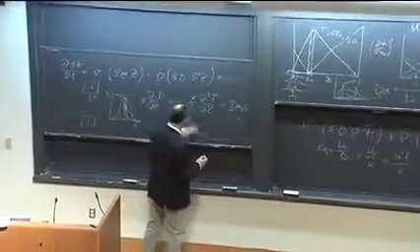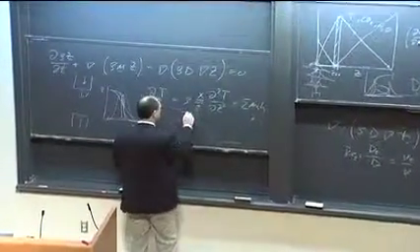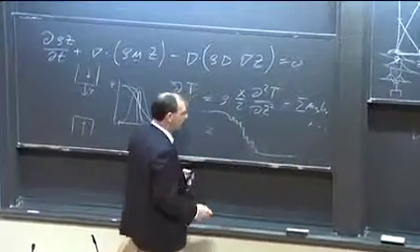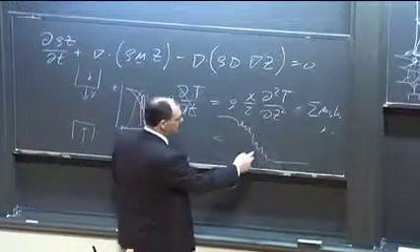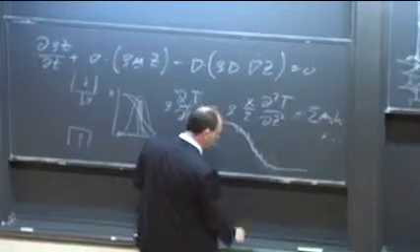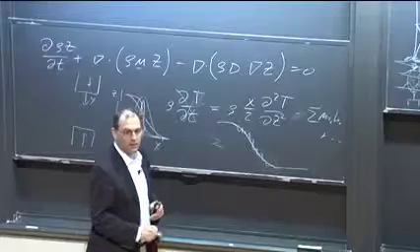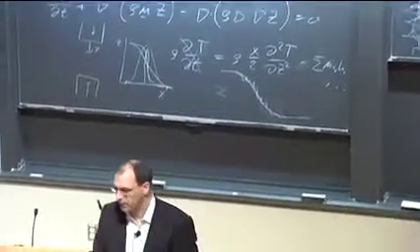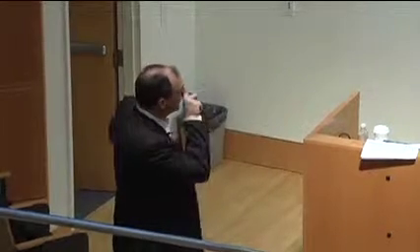Now, in the turbulent flow, it kind of looks more like this. Okay? And what this thing does is it essentially takes out these fluctuations. And anytime you take out these fluctuations, you actually cause molecular mixing to happen. And so this is why this dissipation rate in the laminar formulation and also in the turbulent formulation appears here. So we need to model this dissipation rate.